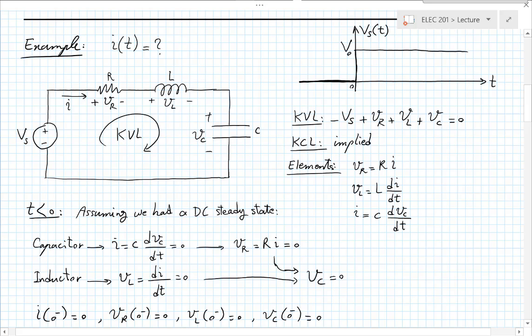The capacitor will start charging up. And so you will have this behavior continuing, where the inductor voltage starts decreasing and the capacitor voltage and the resistor voltage start increasing. And in fact, you can think of this as, well, as the capacitor is being charged up, it's starting to collect energy. And this continues. Now, if the circuit had very small resistance, if R was very small, what would happen is that you would go to a case where the capacitor gets fully charged, and then it will start discharging back, and you would go back and forth between the inductor and the capacitor.